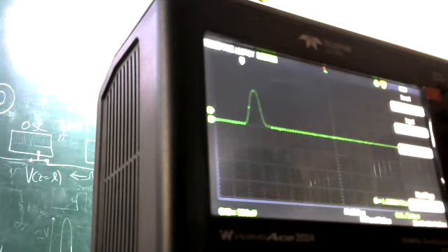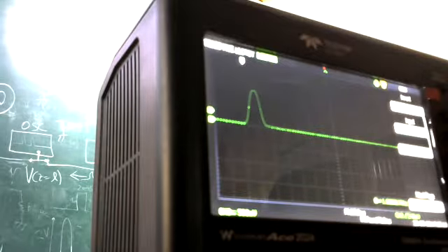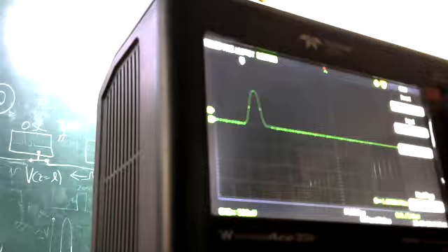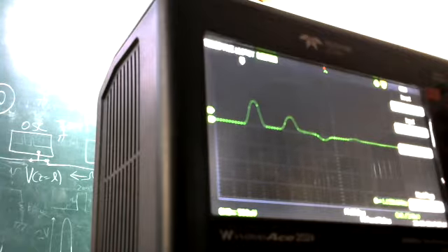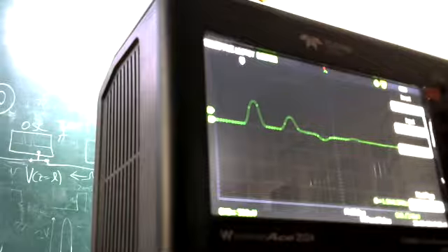So you can say that 1 volt is the incident wave amplitude. In this configuration, where you started from a 50 ohm source and ended on a 50 ohm load, you see a 1 volt signal. Now, when I connect this, the signal seen by the oscilloscope looks like it's 2/3, right? It's slightly higher than half of that.